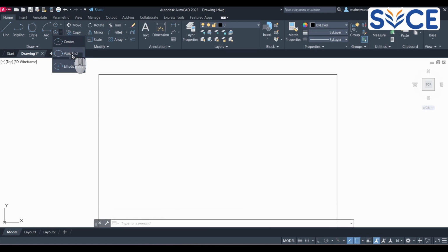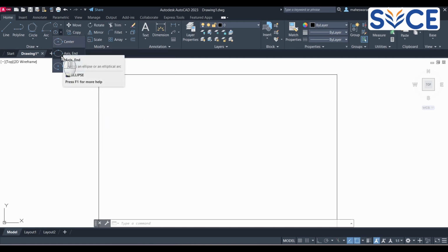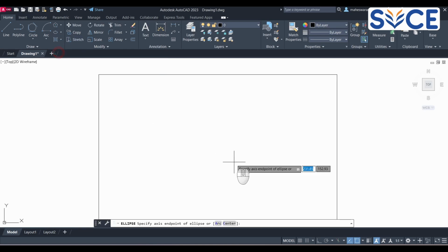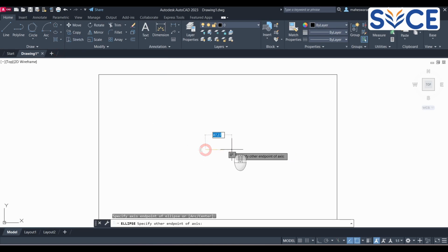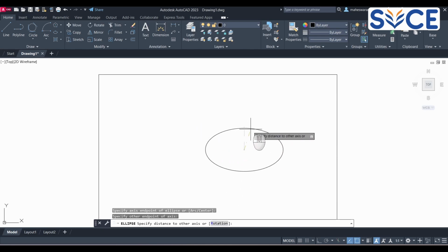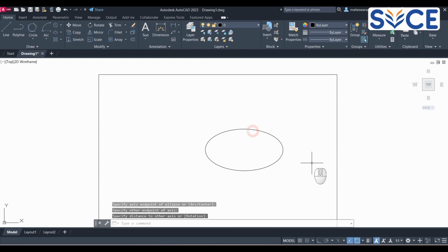Similarly, now if I want an ellipse, go to the ellipse. We have two types of ellipse. Mainly center major axis radius, minor axis radius, and center overall major axis and overall minor axis. Just select it, click wherever you want, move your cursor, click, drag it accordingly, whether I want like this or like this, and click again. Okay, 3 clicks indicating your ellipse.